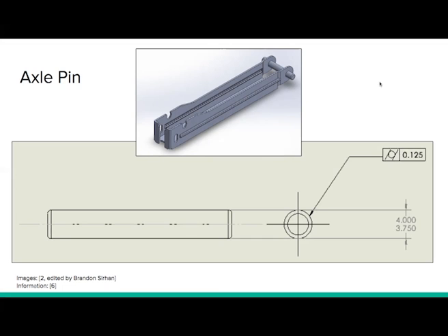The cylindricity tolerance envelope of 0.125 millimeters was determined with respect to the tolerances of the diameter. This value represents the boundary limits used to determine if the form of the pin is acceptable so that it will be able to mate with its counterpart and ensure the assembly will have proper functionality.